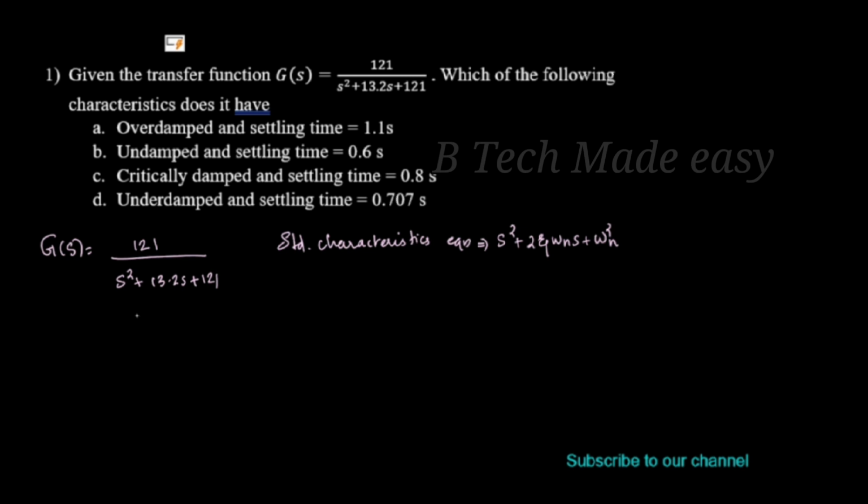from this G(s), we know that the denominator is the characteristic equation. So, we can compare these two equations. That is, s² + 2ζωn s + ωn² is the standard characteristic equation. This will be compared to s² + 13.2s + 121, which is the characteristic equation from G(s).